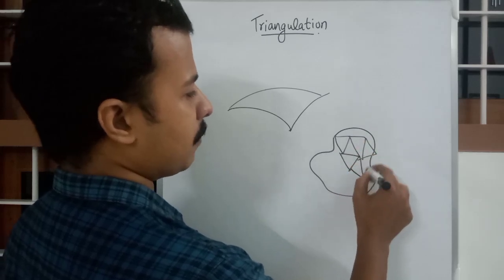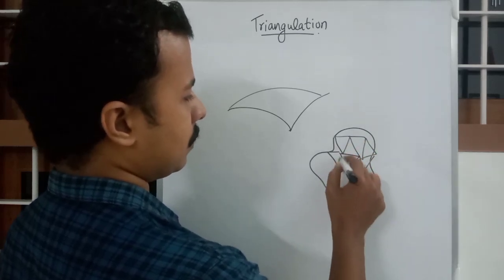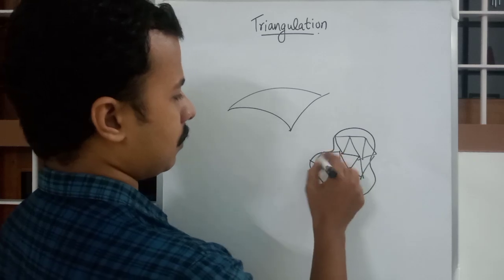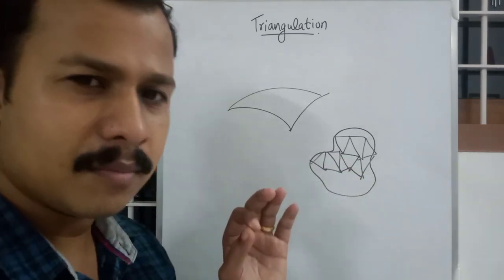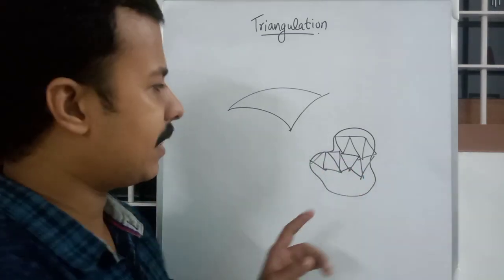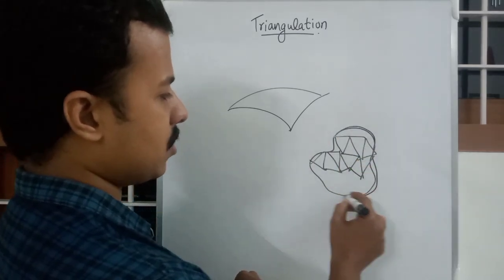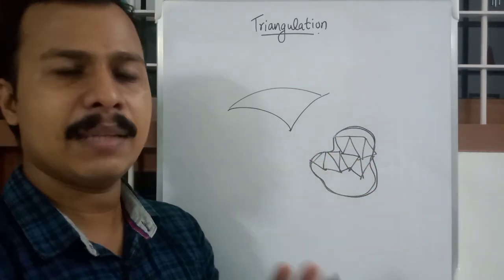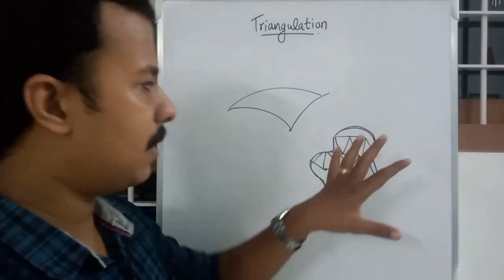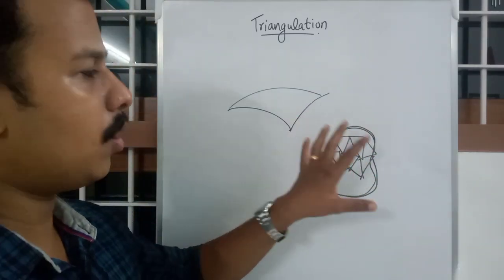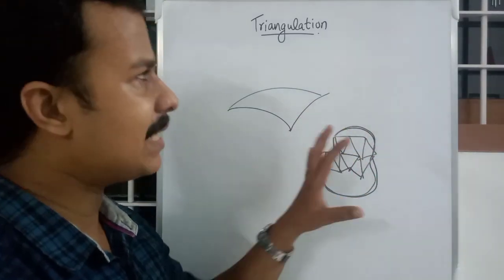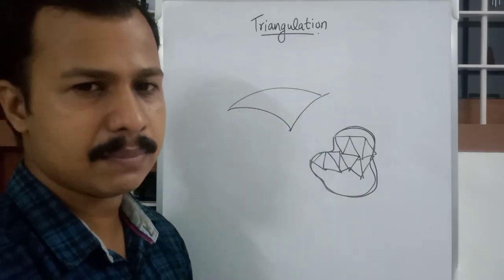There will be n number of triangles, and from these triangles we will calculate each of the areas and add up all these triangles, and thus we will get the plan and the area of a whole district or a whole state. That's why the name triangulation.